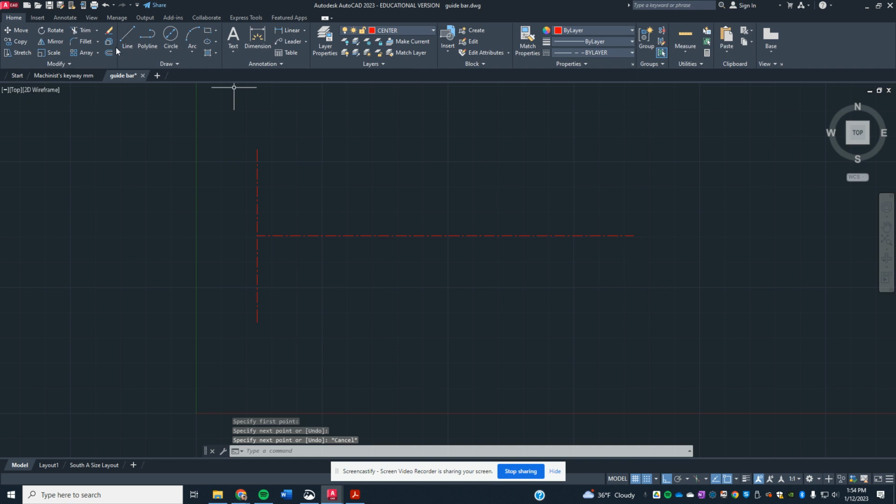All right, I'm going to use the offset command to establish the next 2 center points. Offset, looking at the drawing, the first one is 2 3/4 inches. I'm going to grab this, move it over, and I've got one more that's going to be 2.5 inches away. I'm going to enter to repeat the command, 2 1/2 inch. I'm going to select this, and I'm going to move it over at 2.5 inches.